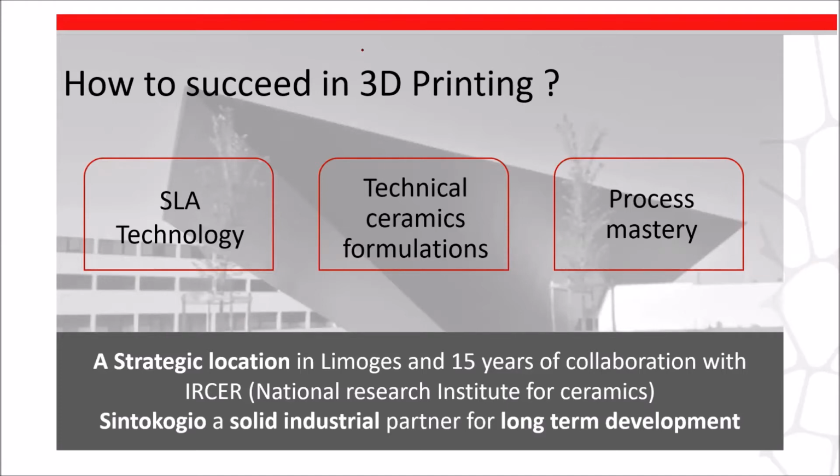We developed during 15 years formulation, technical ceramics formulation, and we worked on the complete process, not only printing, but also all the post-process cleaning, debinding, sintering to obtain a fully dense part with the same mechanical properties of conventional methods.